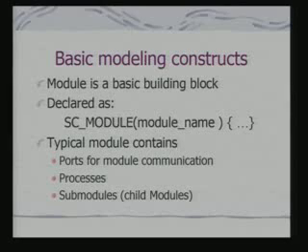So the basic modeling constructs would be the module. You need a feature to define a module. A module is defined using SC_MODULE, and the module has a module name. A typical module, as we have already discussed, will have ports for module communication, processes as well as submodules.